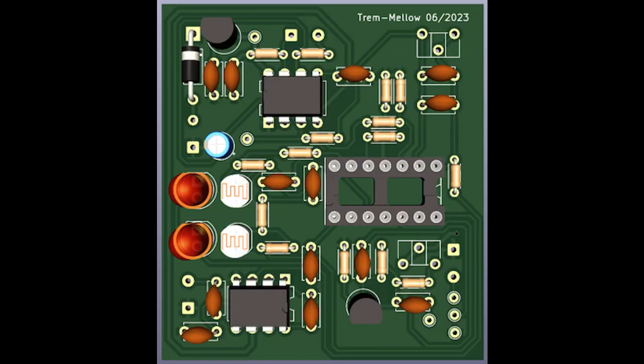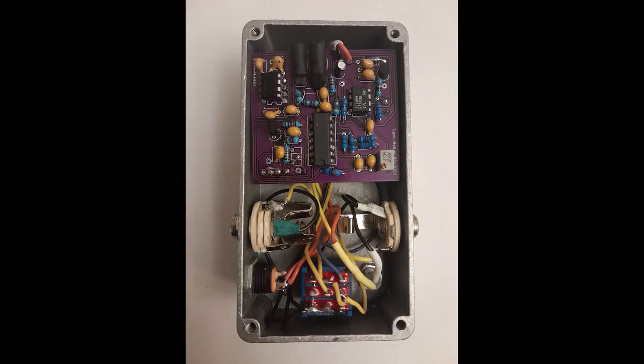The layout of the printed circuit board was dominated by 3 constraints: the size of through-hole discrete components, the selection of only a 2-layer board, and the 2.2-inch width of the enclosure in which it is mounted. The printed circuit board would ultimately prove to be the greatest foil to the design.